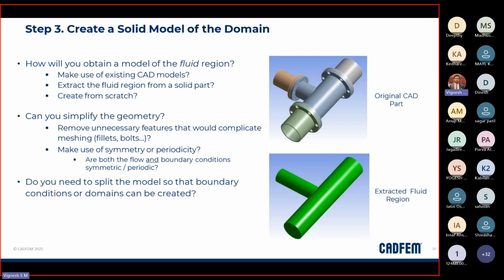Next, we need to create the domain. Once we have planned the domain, creating it is another task. In Ansys, we have an end-to-end workflow from geometry. Once the geometry is ready, we have a CAD model. From domain creation to post-processing, we have a tool. For geometry cleanup and domain creation, we have a specific tool, SpaceClaim. I'll show you during my demonstration. You can use SpaceClaim to create a domain, where the domain will act as the fluid flow over the drone, where we have projection and post-processing that we're going to do.